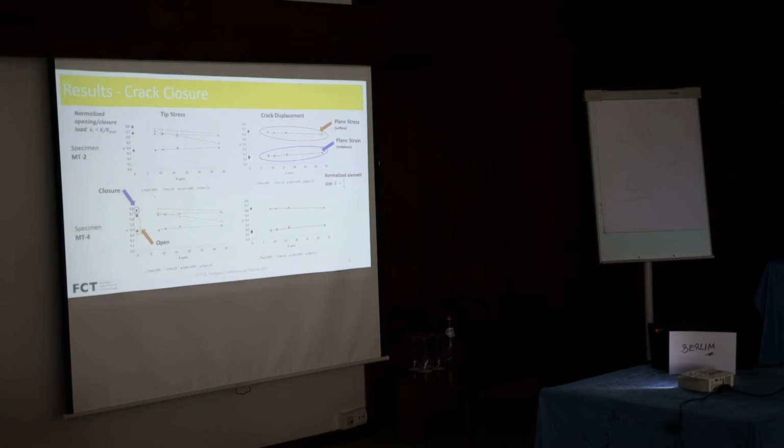Comparing both approaches, we can see that for the tip stress, the closure values are always higher compared with the opening, but for the crack displacement, the results for closing and opening are more or less the same. We observe a difference when we compare the surface results with the mid-plane results, and the explanation is that on the surface we have plane stress, and in the mid-plane we have plane strain.